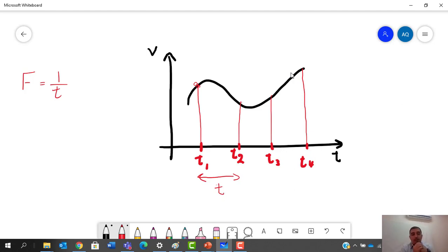Now assume that we want to take these samples. Of course, after we do sampling, we have to do the quantization. In order to do the quantization, I'm going to draw the lines and see the corresponding values on the y-axis. I'm going to come to it later on. But now you can see that if I use only these samples, I'm going to end up with only 4 different values on the y-axis.